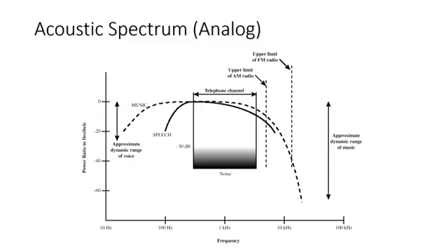As we stated before, analog data takes on continuous values in some interval, the most familiar example being audio, which in the form of acoustic sound waves can be perceived directly by human beings. The figure shows the acoustic spectrum for human speech and for music. Notice that both the x and y axes are in log scales. Frequency components of typical speech may be found between approximately 100 Hz and 7 kHz, and has a dynamic range of about 25 decibels. A shout is approximately 300 times louder than a whisper. Another common example of analog data is video, as seen on a TV screen.